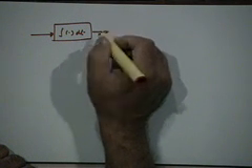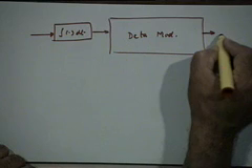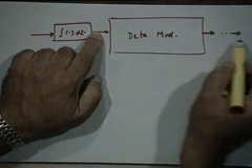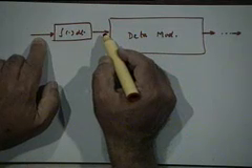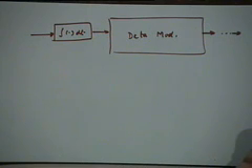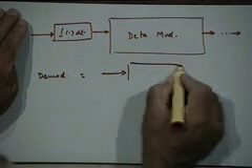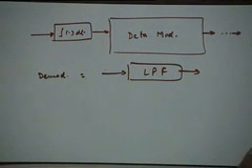You have an integrator and you have a normal delta modulator, right. And now tell me what will be a demodulator now. If I want to reconstruct this, I must have the integrator followed by the low pass filter, but I am not interested in this, I am interested in this. So, I have to differentiate the signal. So, integrator followed by a differentiator means I do not need to do anything, right. So, demodulator is simply a low pass filter, very simple demodulator. So, you still have a binary representation, everything is same, but you get both the advantages, a simplified demodulator and you remove that problem of being proportional to the derivative.